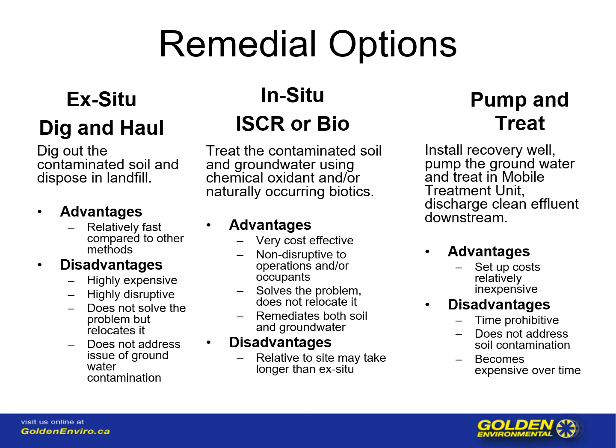Also, one must consider the soil oxidant demand. Oxidants are indiscriminate. They oxidize anything that they come in contact with, which includes the soil. Therefore, depending on the lithology, each soil type will demand a level of oxidant different from another type of soil. This also must be calculated into our process so that we make sure we get enough oxidant in order to cover the soil oxidant demand as well as the contaminant oxidant demand.